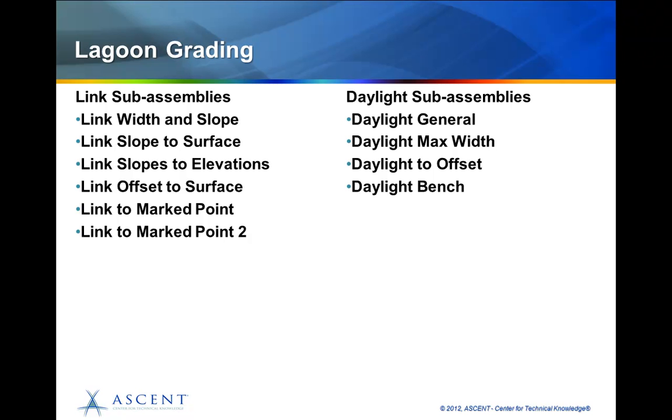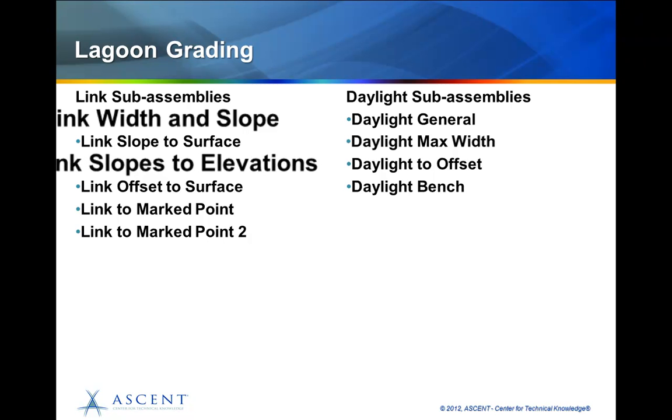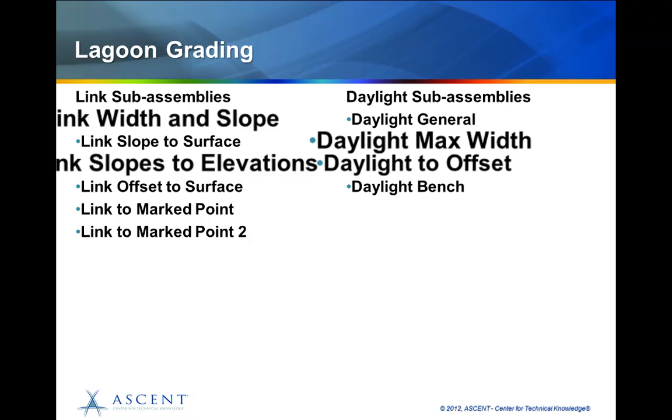This is a list of all the different sub-assemblies that I talk about, but you only use a certain percent of them. In the course we use the link, width, and slope, the link slopes to elevation, the daylight max width, daylight to offset, and a daylight bench. But the reason I've talked about the other ones is so that you understand how they work.